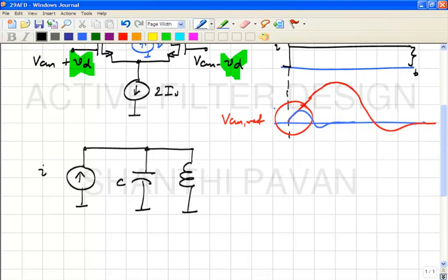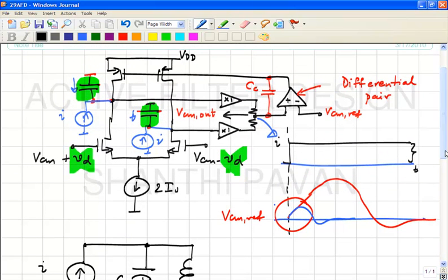No, the voltage will go to infinity, isn't it? If the slope goes to infinity... no. See, it cannot be a step increase because the feedback loop is still sleeping, right? So this voltage is still, it doesn't know anything. All that you have done is suddenly push in two currents. If these integrating capacitors were there, that current would all go into the integrating capacitors and the output would ramp up, right? The steady state value of that ramp in principle is infinity, correct?